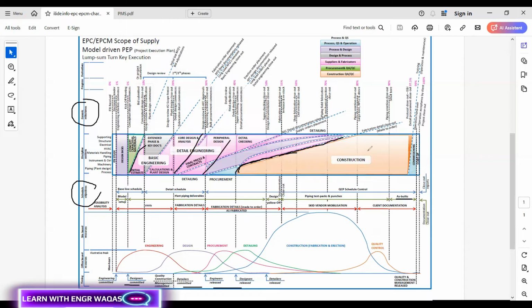After understanding all these things, of course, you need to write down everything along with this video. You need to pause it and write down your milestones. This is a complete case study you can implement on any project, to make your concepts clearer. But in our project as a planning engineer, you are supposed to provide the progress. So here are the progress derivatives: when your feasibility analysis is done, it is 1%; then your decision to tender, then 5% for the kickoff meeting, 10% for conceptual design closeout, and 20% there.